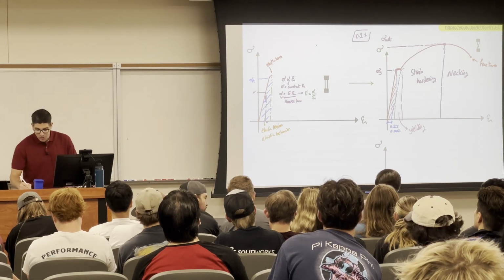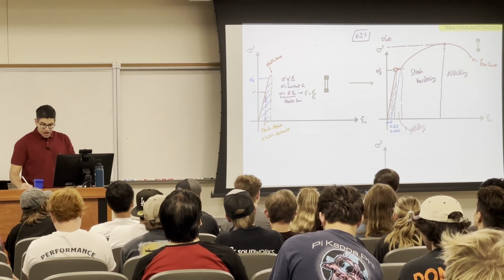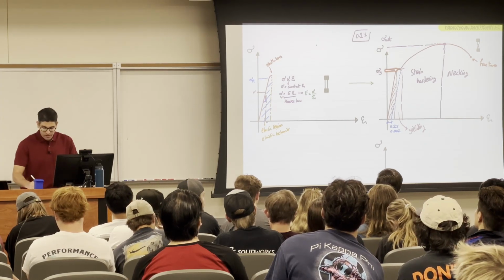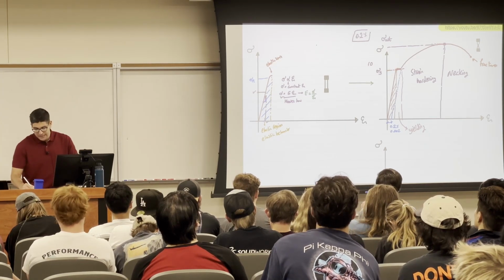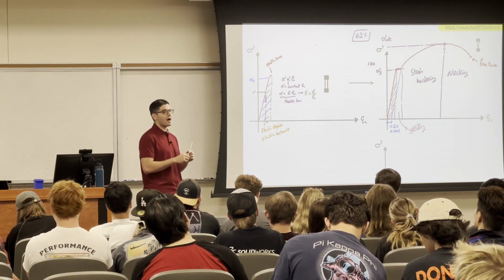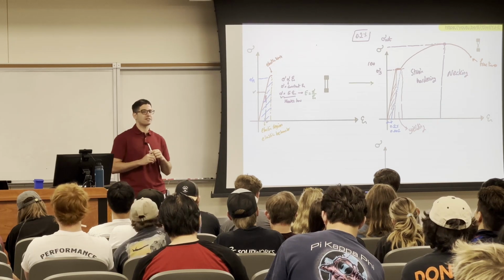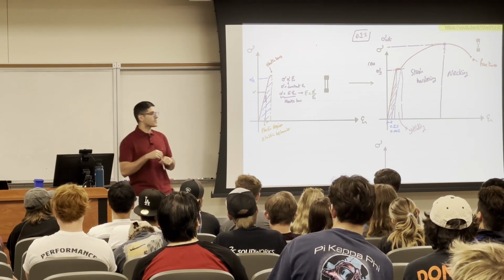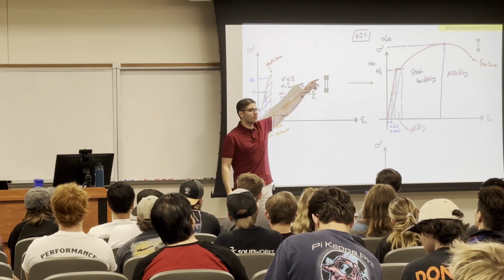I know the yield stress, which is well defined in the stress-strain curve, for example for a material it's 100. Will I design on the 100, or will I take a factor of safety of 2, for example? And when I take a factor of safety of 2, will I design on 200 or 50?